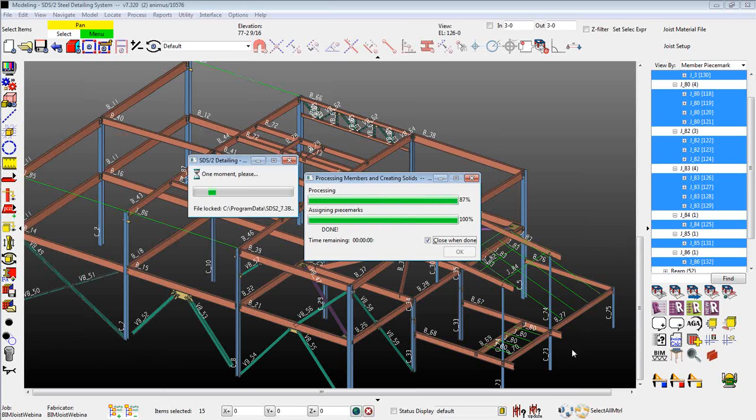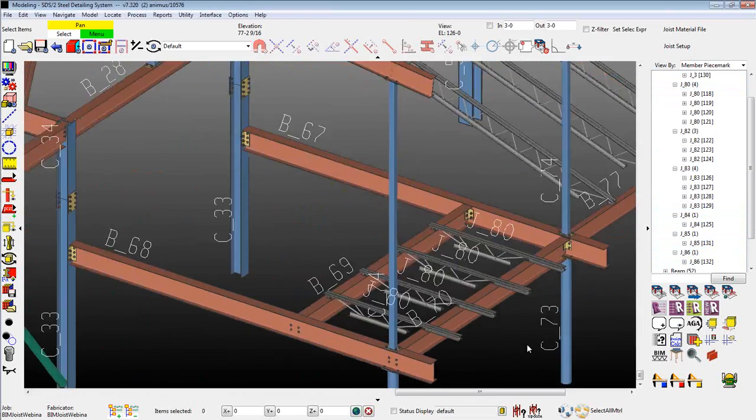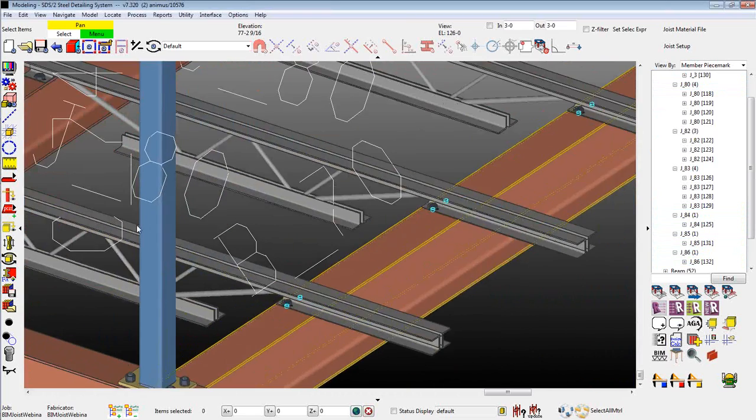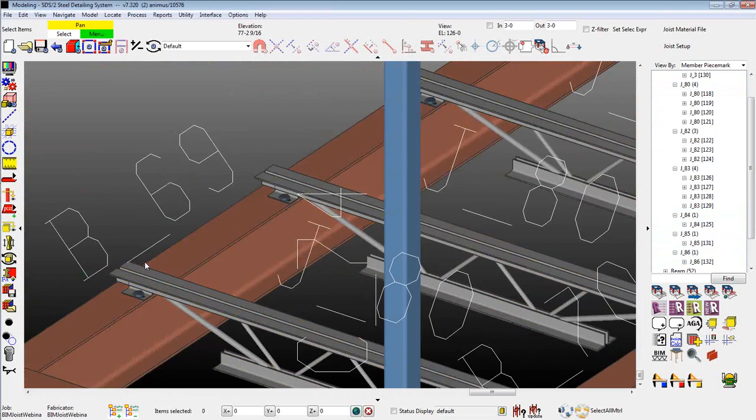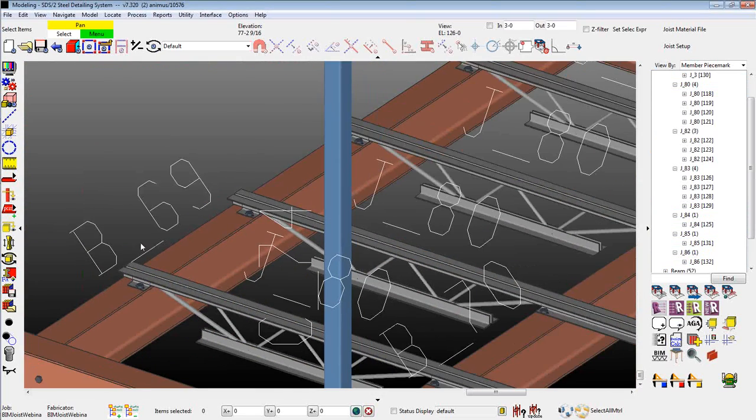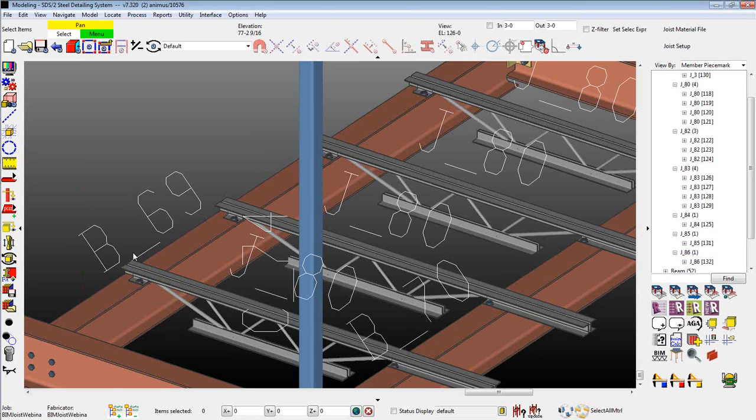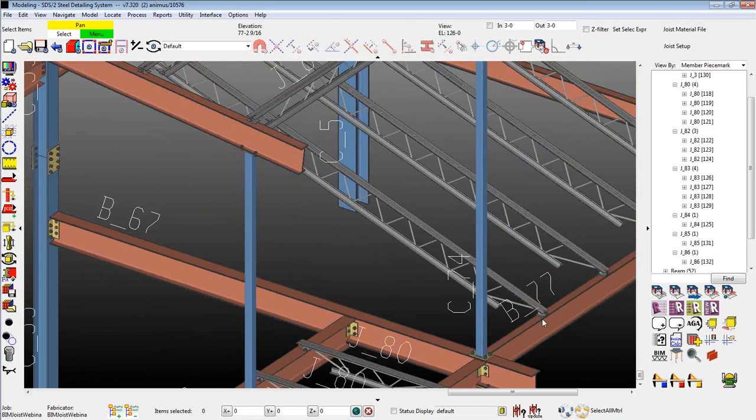The only ones that we should see get updated connections are going to be my 10K ones down here framing to these beams. The reason is because in that setup, I changed the joist to beam top flange for 10K1 sizes only to be bolted.